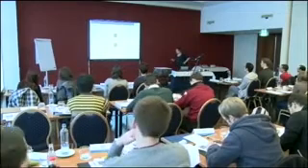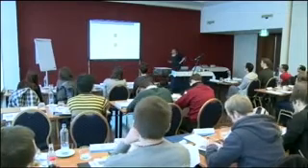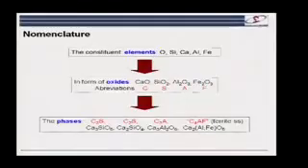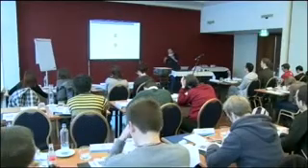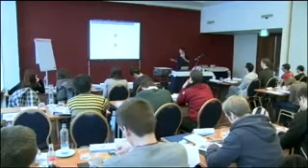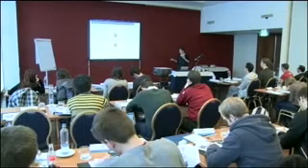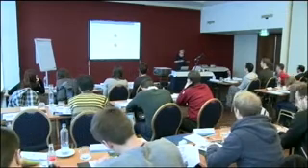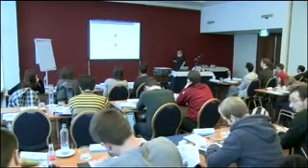Now, this ferrite phase is always written C4AF, but in fact, it's almost never C4AF because really it's a solid solution, more correctly written down here, where aluminium and iron can be interchangeable. So you can actually get a very wide variety of compositions going from about 2/3 alumina to 1/3 iron oxide, to 1/3 alumina to 2/3 iron oxide. But you'll always see it written and always talked about as C4AF.